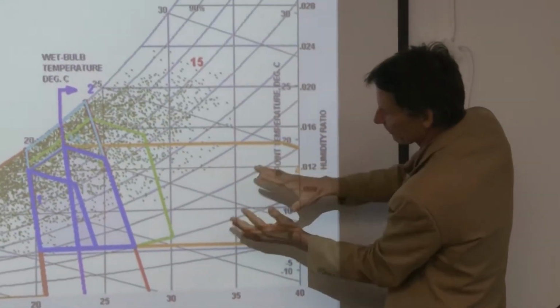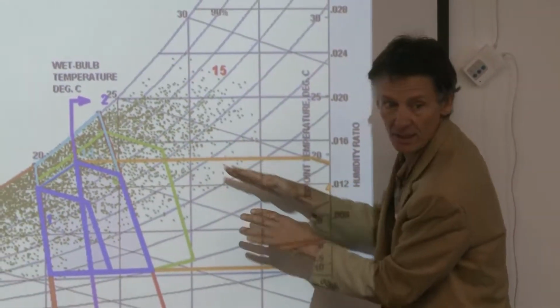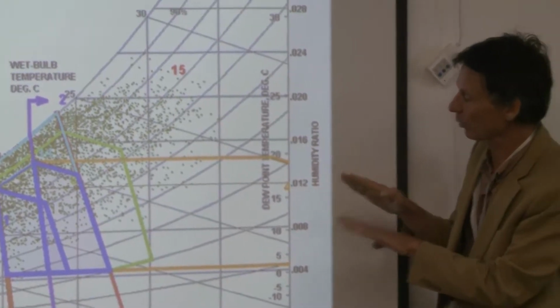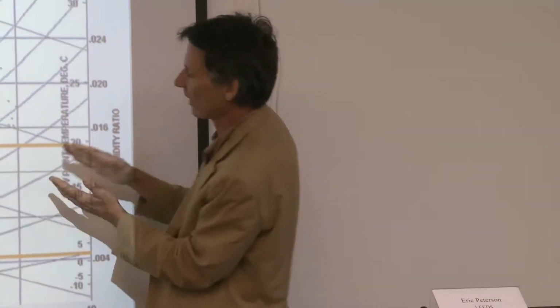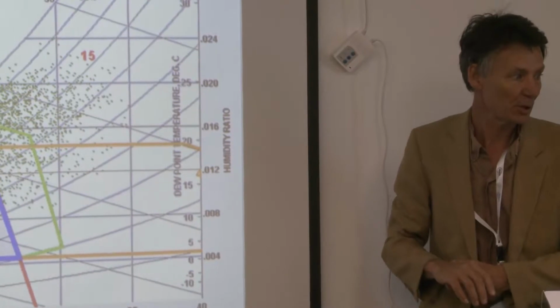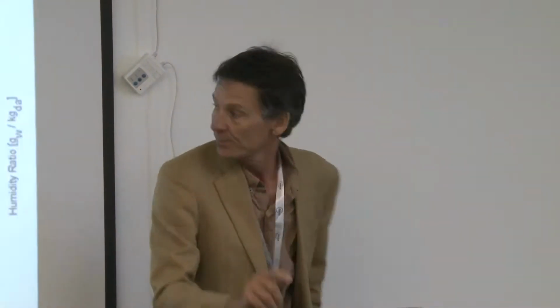Evaporative cooling, unfortunately, has limits about where the wet bulb lines come. And direct evaporative cooling, I'm really keen on it where it works, and that's something I've tried to conclude in my paper, where it would work. But in a lot of places there are times when swamp coolers just don't do it. In Arizona, the monsoon comes, you're going to need some DX on point. These are these points up here.